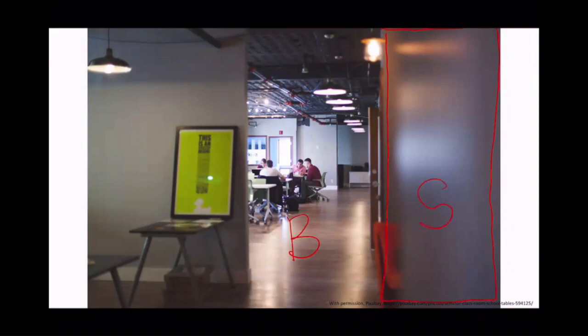And the catch is, if you choose not to separate them, you have to treat the whole building as if it's the more restrictive occupancy type. So you have to treat the whole building as S, because in most cases S is more restrictive than B. And when you have to do that, like under what conditions? Well, you have to do that when you're figuring out the construction type.